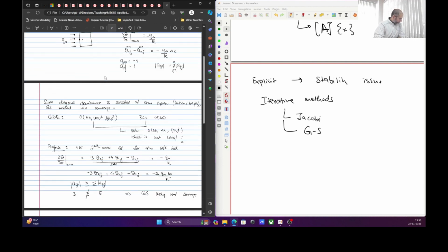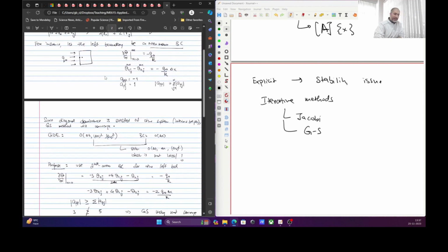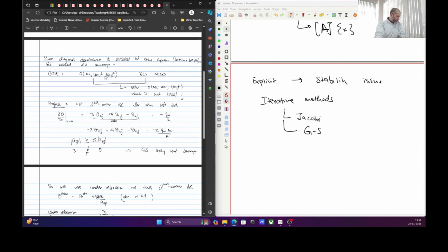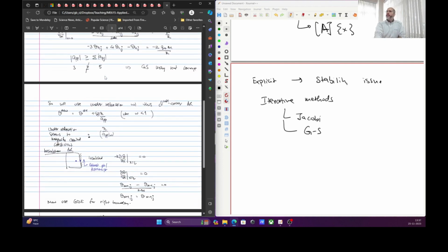Okay. So lecture 15 was where we talked about diagonal dominance, learned about the idea of boundary conditions, higher order boundary conditions sometimes resulting in the lack of diagonal dominance. So one has to be careful with the use of boundary conditions. And one way to get past that is to use under relaxation. If you use under relaxation, that in a way is elevating your central coefficient, and that results in diagonal dominance in the algorithm. So that's one way to get rid of these conditions.